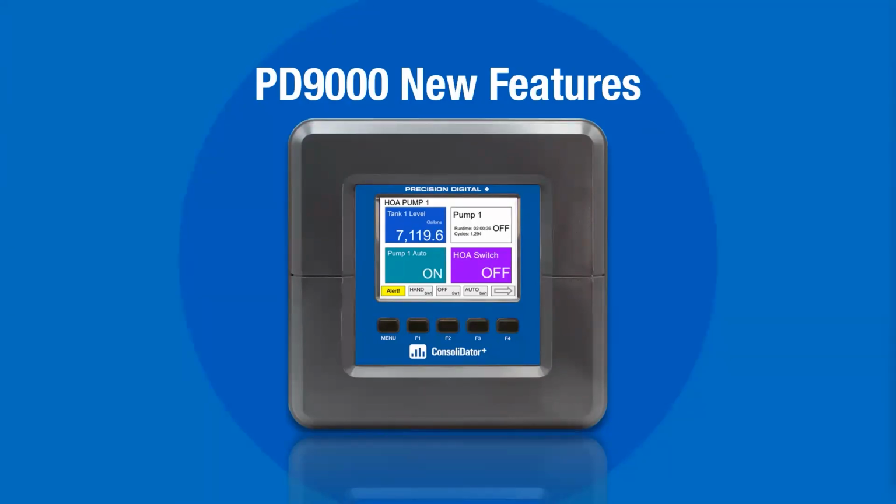So the answer to your question is yes, we can do flow rate totalization. You don't actually have to use the timers for that. There's a total function that is its own function, and you just direct it to a rate channel, tell it what units you want, and it will display and monitor that total for you. And if you then want to have some kind of a relay or an output assigned to that, that's perfectly fine. You can have a relay assigned based on when a certain amount is totalized. You could have that relay assigned as a sample relay that triggers every so much total that has been accumulated.